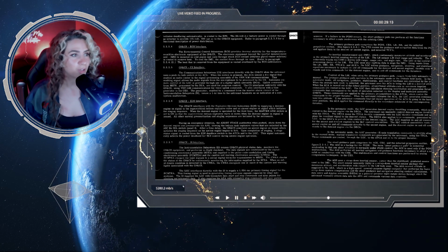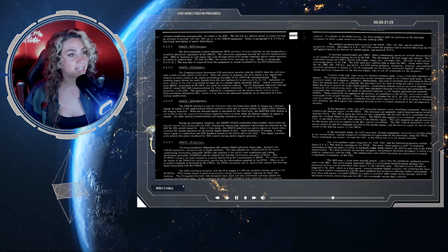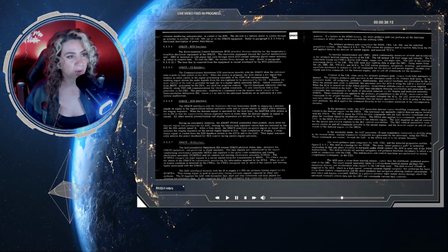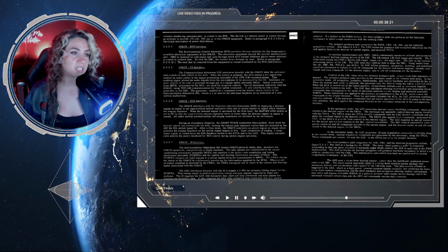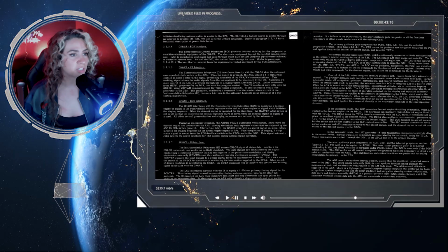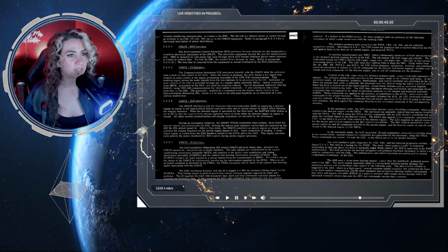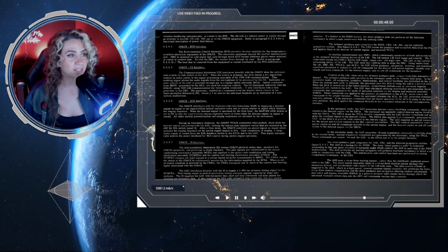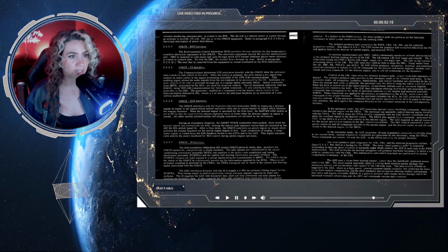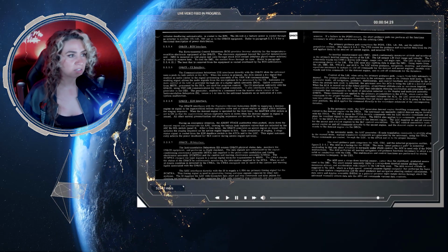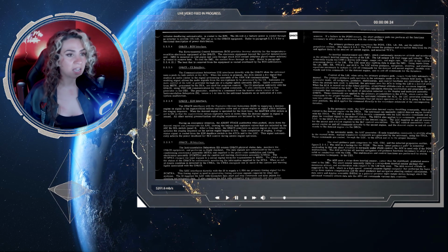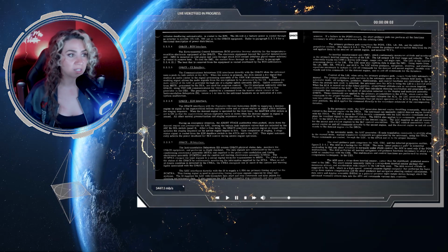Okay. When the attitude hold mode is selected, the astronaut uses the ACA to bring the LM to the desired attitude. When the ACA is moved out of the detent position, proportional attitude, rate, or minimum impulse commands are routed to the LGC. The LGC then calculates steering information and generates thruster commands that correspond to the mode of operation selected via the display and keyboard assembly, the DSKY. These commands are applied to the primary preamplifiers in the ATCA, which routes the commands to the proper thrusters. When the astronaut releases the ACA, the LGC generates commands to hold this attitude.